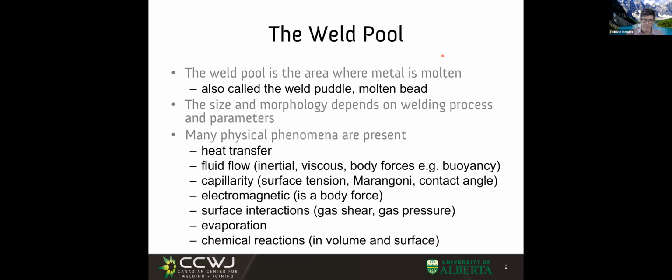For some cases of additive manufacturing, this might not be the case. For example, additive manufacturing in powder beds, in which the laser causes very small local melting and the cooling rates are enormous, there might be some deviations from melting temperature, for which there are formulas and for which our predictions of heating and cooling rate are still very good.